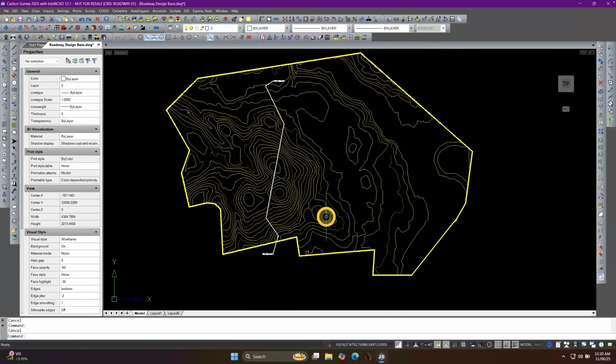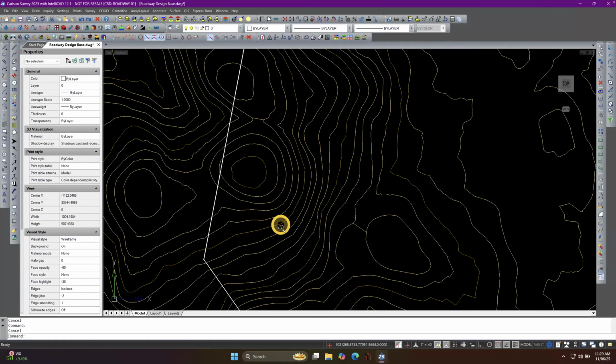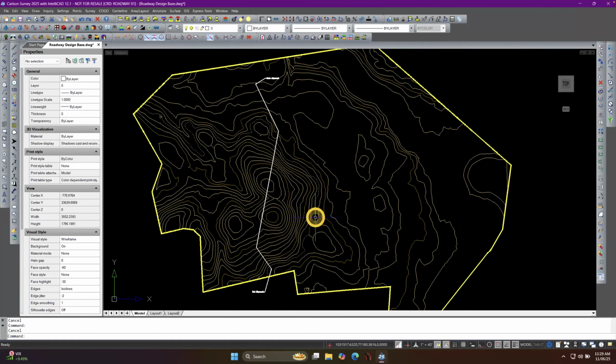So there's a 5 foot difference in elevation between those contours. Now this would be a very steep terrain if I were to actually have something like that. I would expect this to have been created more like a 2 foot contour interval. But anyway, here are our contours. We know what the contour interval is.